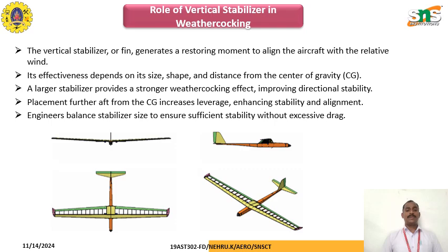The role of the vertical stabilizer in weathercocking. The vertical stabilizer, or fin, generates a restoring moment to align the aircraft with the relative wind direction. Its effectiveness depends upon the size, shape, and distance from the center of gravity.